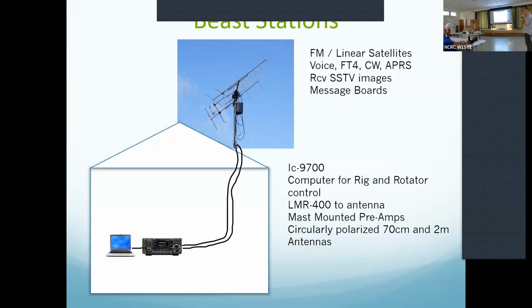Now, you obviously can't do that with static antennas like that. So what they do instead is put a vertical and horizontal together. They're spaced about a quarter wavelength apart. And when the signal goes to one, it has a special phasing line, then it hits the other one, and it kind of spins it.